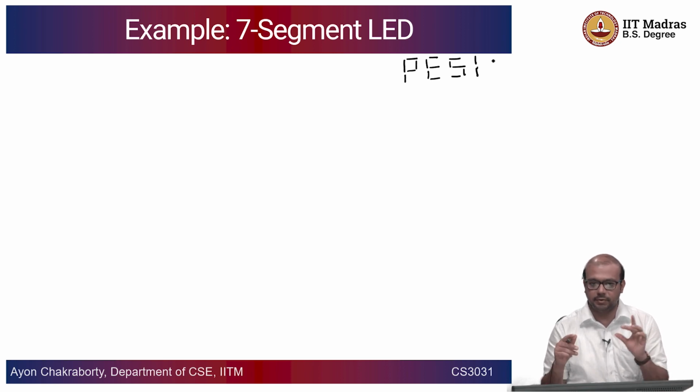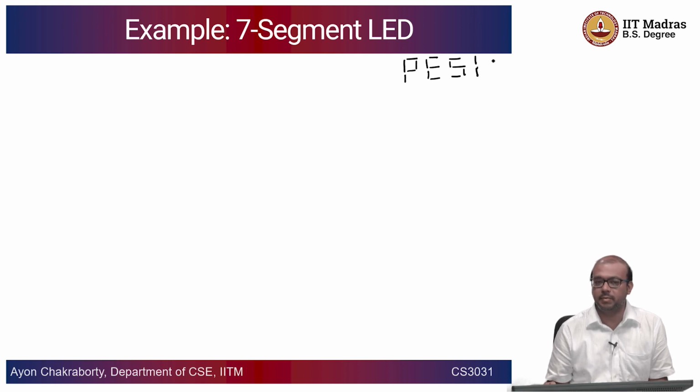Of course, you need to have multiple LED segments to show multiple outputs, but the LED driver is not going to change. Because you are restricted to only 4 outputs, how many bits should you require to encode them? Log 4 to the base 2, which is 2. Only 2 bits are required.